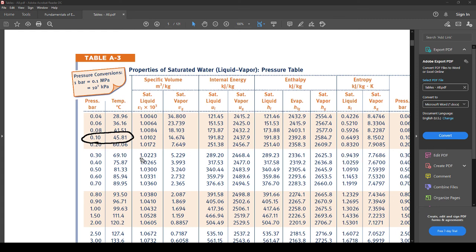What state are we in? Are we saturated? Are we superheated? Are we subcooled? What are we at, guys? Anybody know? Using what I have circled, temperature 2 is 45 degrees. We are subcooled, that is correct.